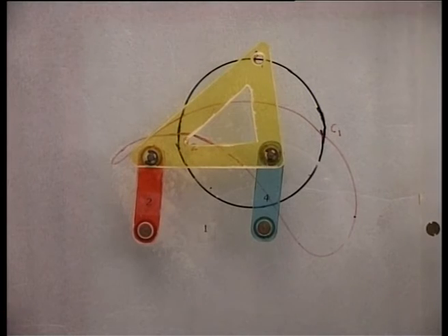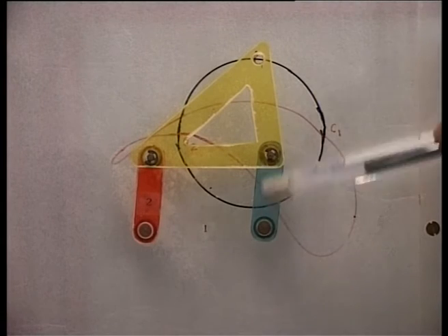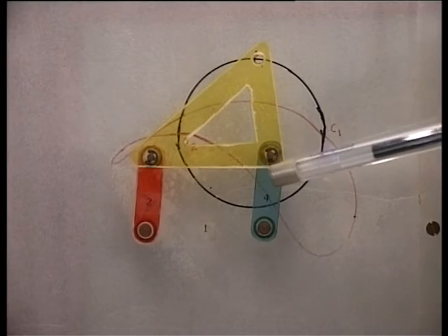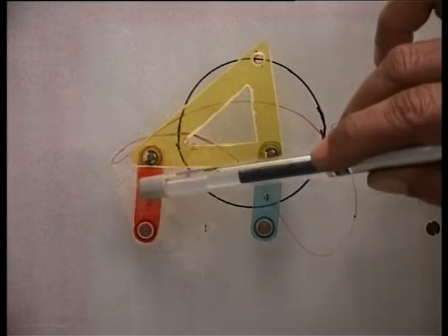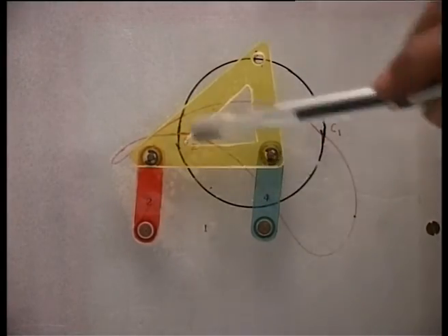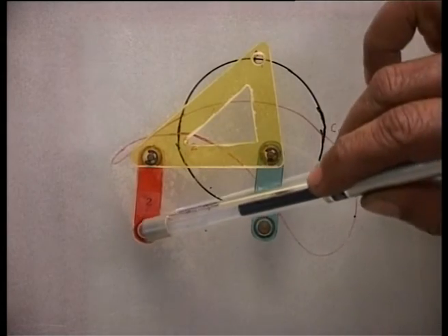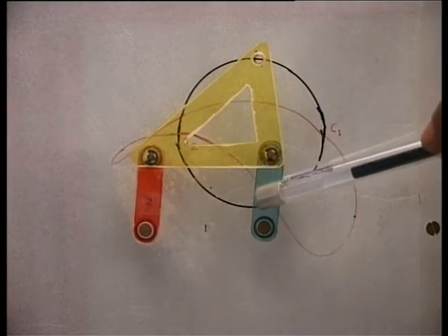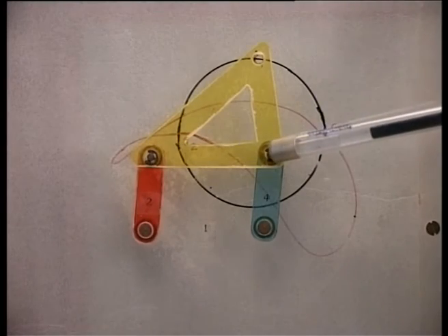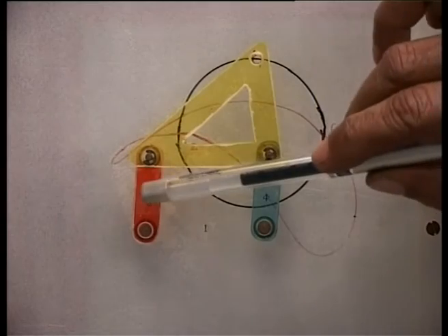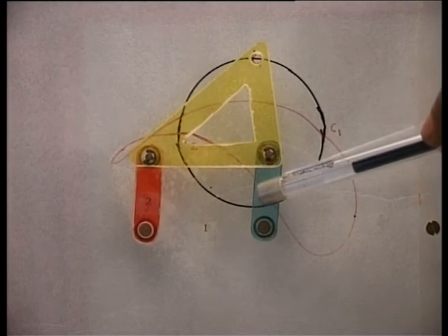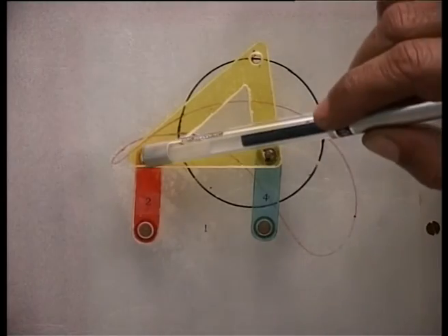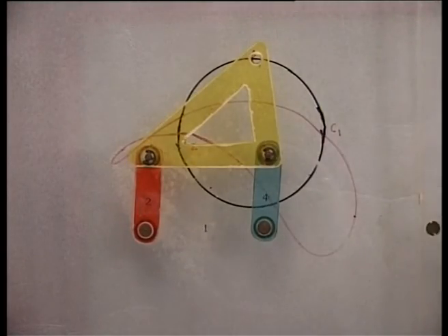Let us now look at the model of this transition linkage, that is the special situation of a transition linkage. Here, these two links are of same length, which are opposite to each other, and this coupler length is same as the frame length. That is, we have a pair of L min and a pair of L max. However, because these two equal lengths are not connected directly, they are the opposite sides, it forms a parallelogram and we call it a parallelogram linkage.